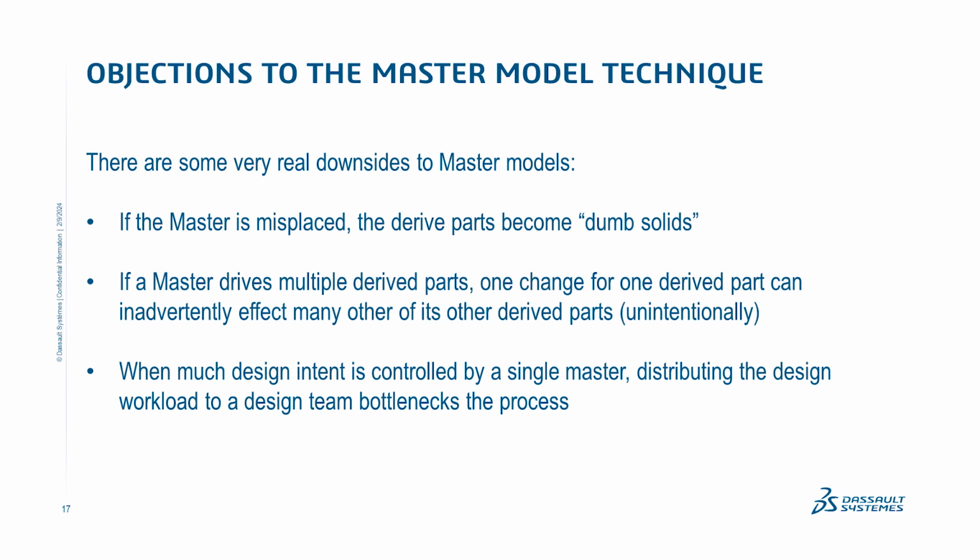We talked about the misplace of the master model, and you just don't want to do that. If you're on a PDM system, you want to make sure that part is checked in and there's multiple revisions of it. So a master drives multiple parts, and one change in a master model can inadvertently and unconsciously change multiple parts. So this is a real issue, and you need to be careful of it.